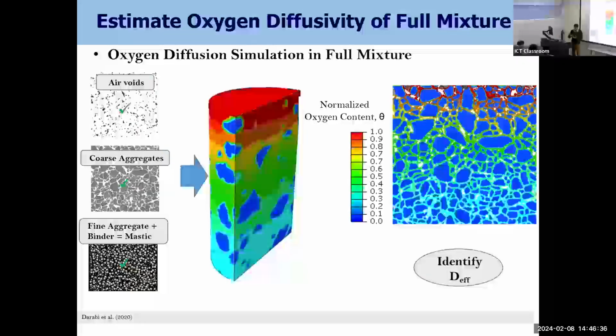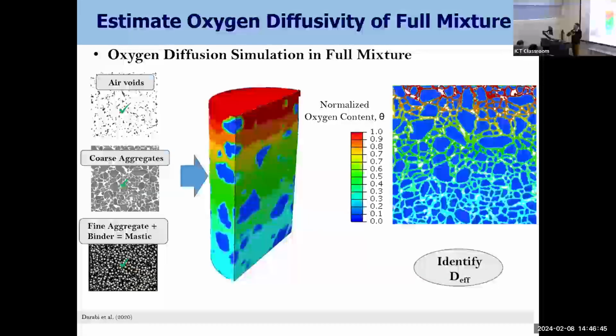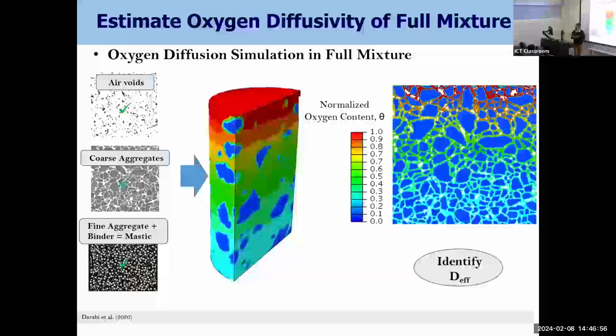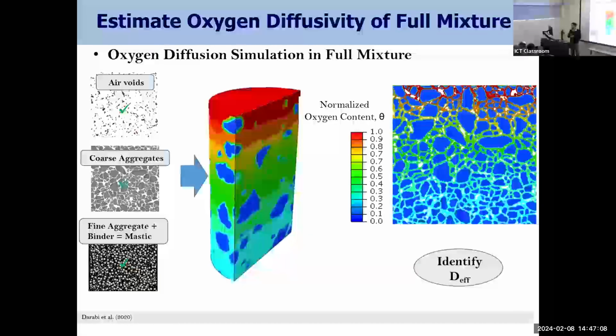In the past, the way that we accounted for that was to incorporate the evolution of the oxygen content or the oxidation level into our damage model. But then we said, well, let's see what it does. It is actually making the material harder and more brittle. So why don't we just change the compliance terms in viscoelasticity, which are those D sub n's.